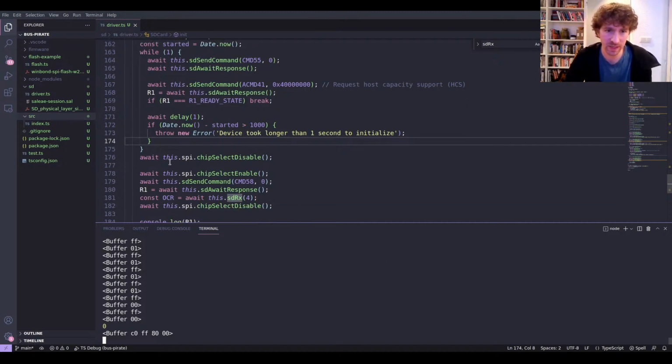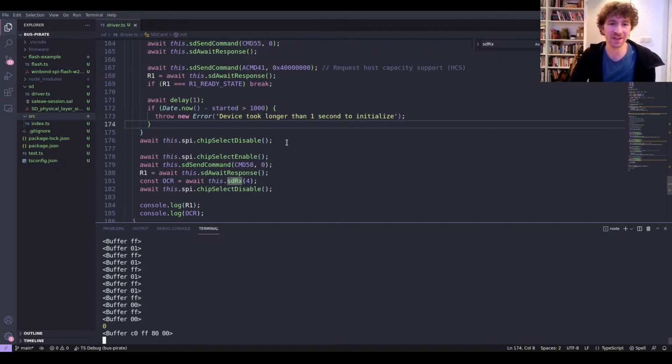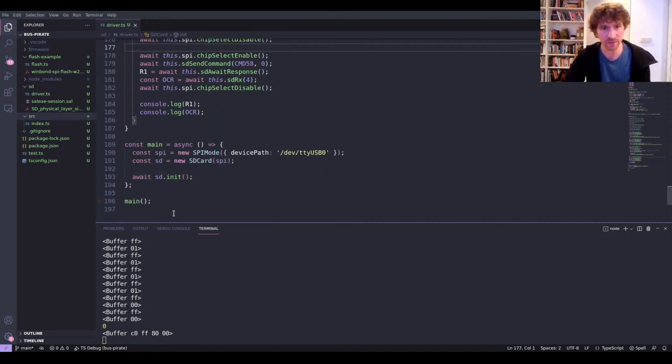So in this case, the trouble was that the underlying library has a default argument for that transfer function, which says automatic chip select control. I'm definitely going to change this now because I see how annoying it is if you're working with it. I'm going to force the user to provide that, because this is how you can avoid that kind of error in your API. So lesson learned. Quite happy with that. I'm glad that we got this running.